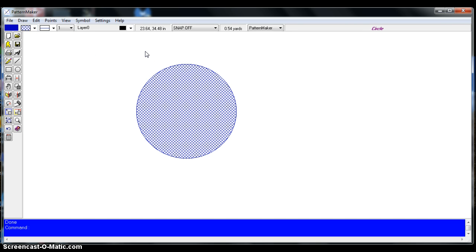The circle is a closed polygon with 8 points making up 4 arcs. You can choose any of the editing functions you've already learned. Let's stop and check out the vertices real quick. F5 is our hotkey that shows our vertices. Can you see the blue ones? It's hard to because the object is blue too. But there's 4 of them positioned on the border of the circle. And then these green X's out here are the control vertices for the arcs. I'm going to go ahead and turn that back off, F5.